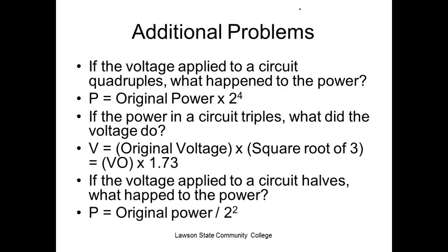So you've got two options. The Motoman robot does it a little differently. It's not actually a circle, it's an arc. If I'm going to do an arc like this, I have to identify three points, P1, P2, P3. Robots do it differently. Like the Motoman, you have to teach the Fanuc and the other robots, that would be your first point. So wherever you're at, that would be P1.